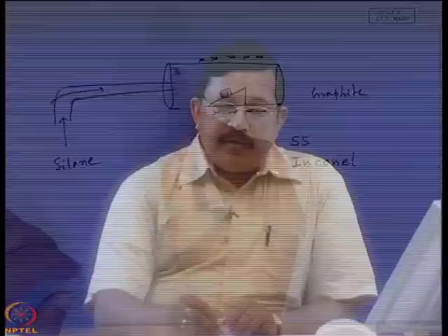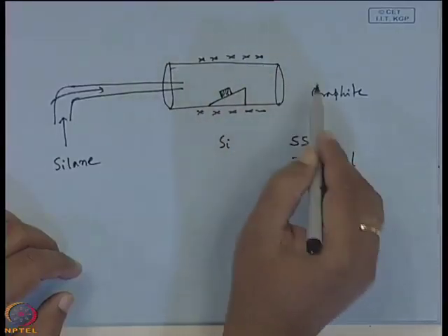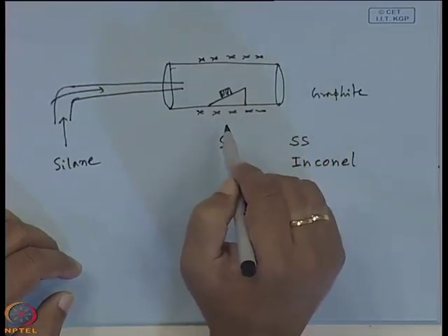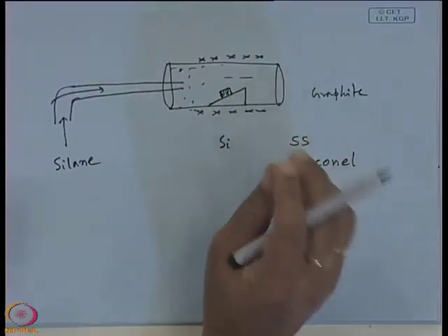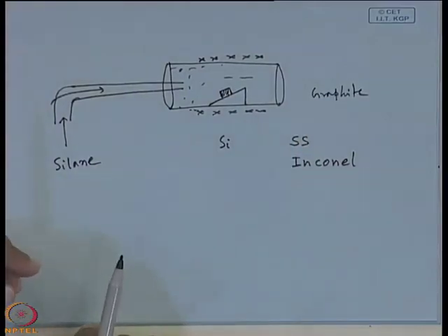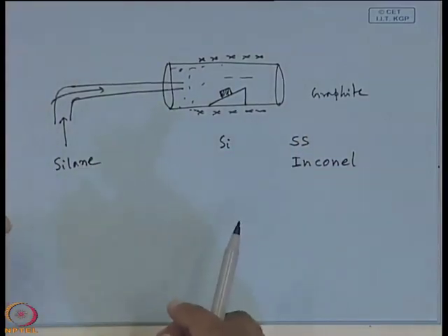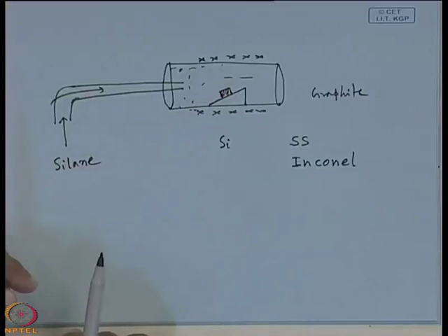It is because if the whole volume of the reactor chamber is heated, then before reaching onto the substrate surface, reaction will start. So, on different parts of the reactor chamber, there will be the reaction, but that will be a loss for you. Material will be lost, because you want the film to be grown on the substrate surface only.